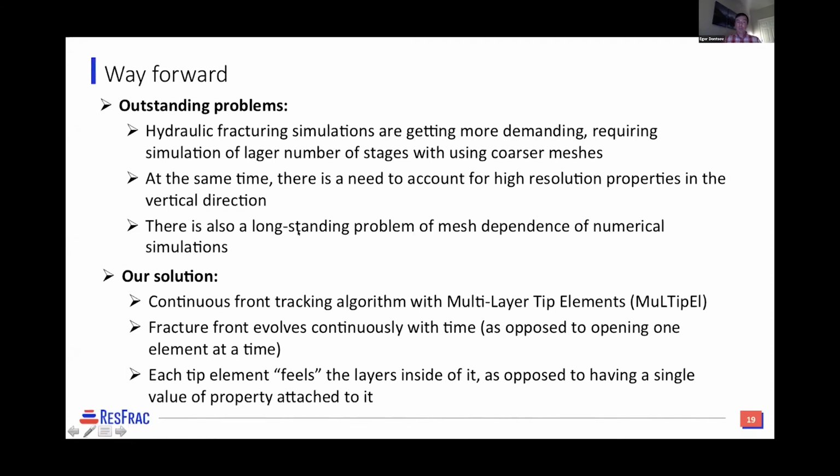And the solution, which is coming very soon in ResFrac, is this continuous front tracking algorithm with multi-layer tip elements, right? This is a new algorithm which allows us to evolve the hydraulic fracture front continuously, as opposed to opening one element at a time, right? And because you evolve the fracture front continuously, you know where your fracture front is located relative to your layers.